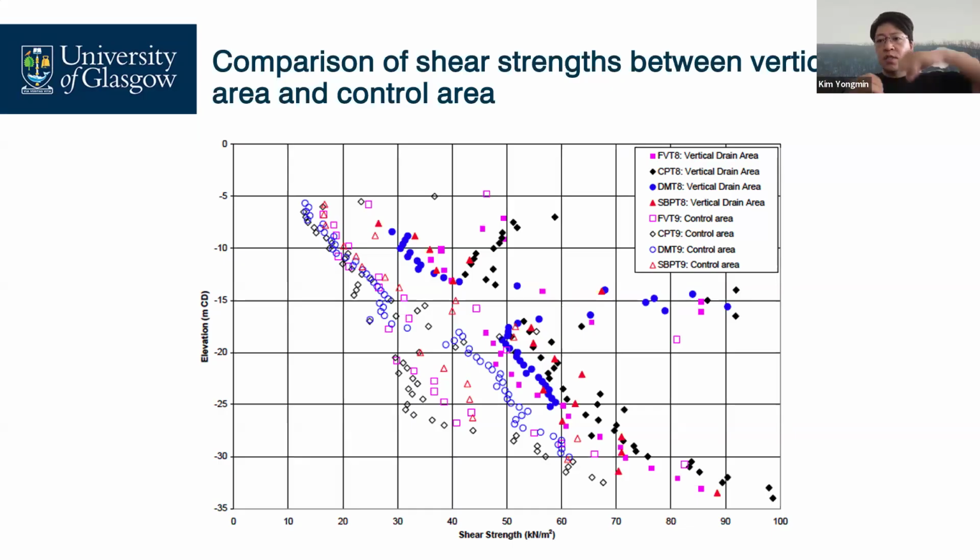What is the shear strength? This is the soil layer, and then we press, and it probably fails in a shear way, sliding on each other. This is shear behavior. Most soil fails in the form of shear failure. That's why our soil's shear strength is important.